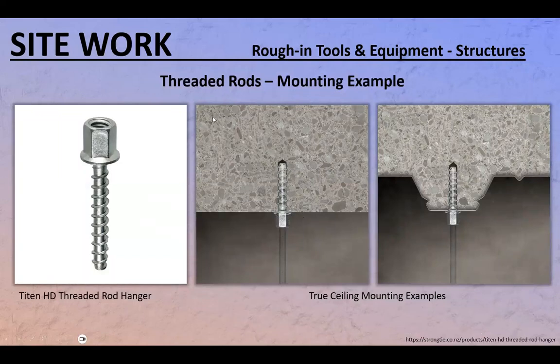This would be, well, threaded rod hanger. You see here, this bolt, this nut here, has a thread inside. You screw that into concrete and you mount the threaded rod. You just turn it right into that, and voila, there you go. Here's your threaded rod hanging. So threaded rod hangers are quite common.